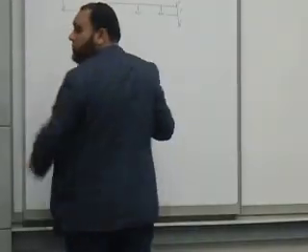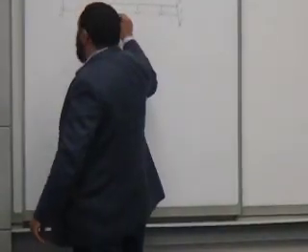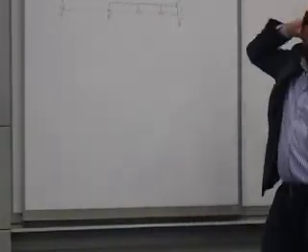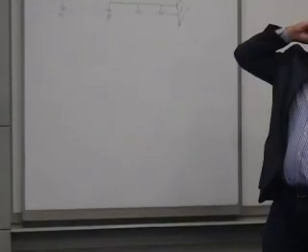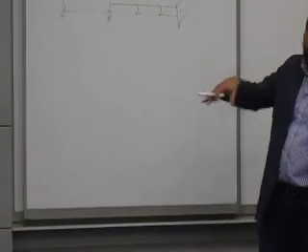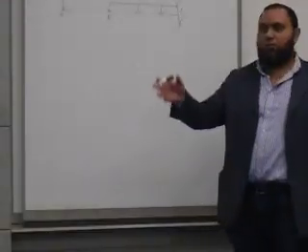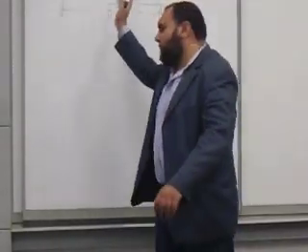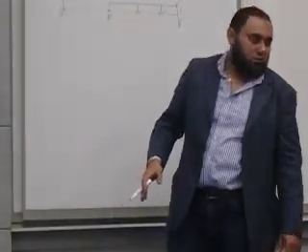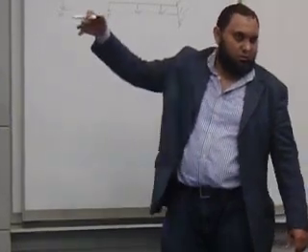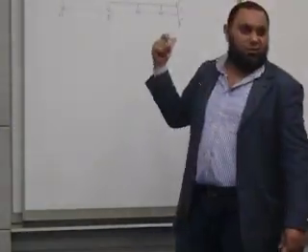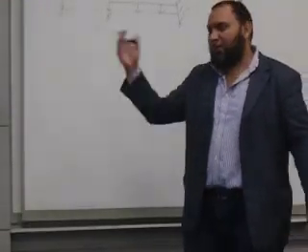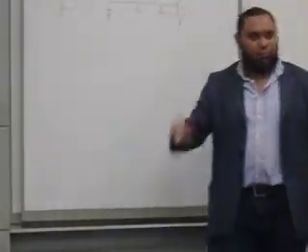We need the internal force. First thing, we need to get the reaction. Right? But wait, not always. We will not always need to get the reactions. Maybe you will need it, maybe not. If I take a section and I look left, actually I don't need the reaction because there is no reaction there. But if I'm taking a section and looking right, I must get the reaction. But let's keep this reaction thing on the side and do it without the reaction.